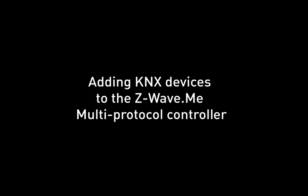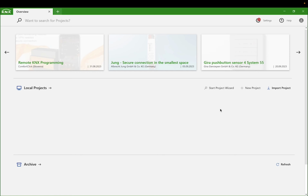Adding KNX devices to the Z-Wave Me multi-protocol controller. Configuring the device in the ETS software. Here we'll show you how to add KNX devices to the Z-Wave.me multi-protocol controller, and then interact with them from the Z-Wave. Launch ETS program on Windows.